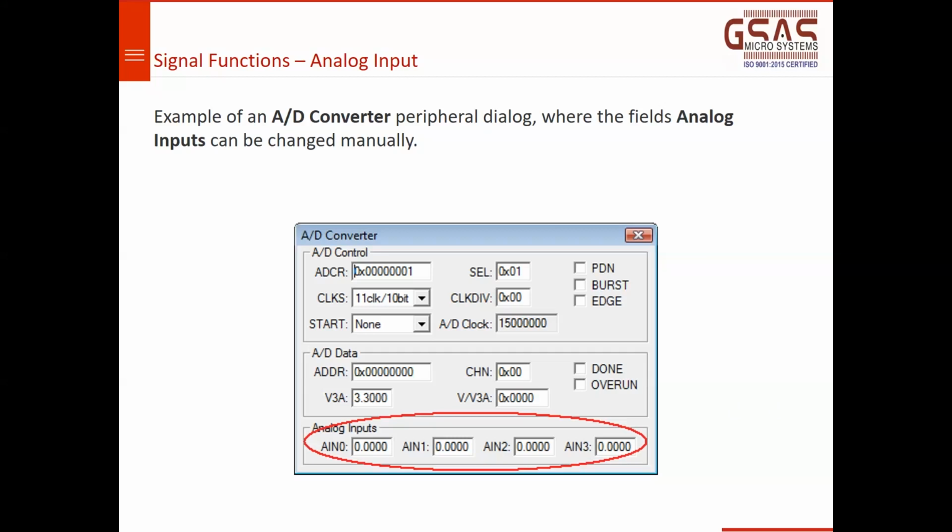This is true for any processor, but you have to ensure that whatever processor you have selected in Keil is well simulated in the Keil IDE. The current version, MDK version 5, given by ARM, does not have simulation support, but MDK version 4, µVision 4, has simulation support for the earlier devices that ARM had supported in Keil MDK.